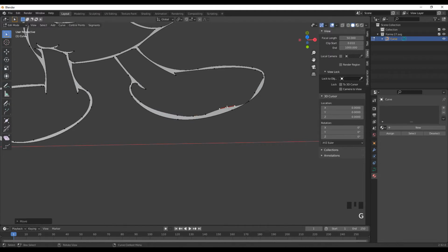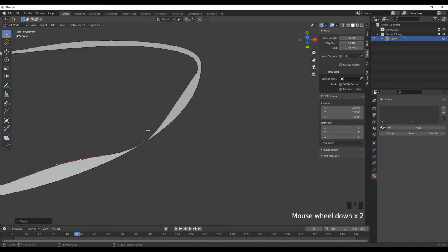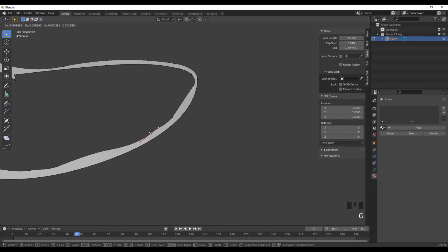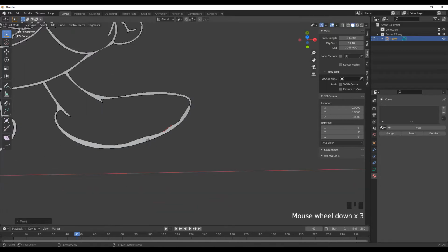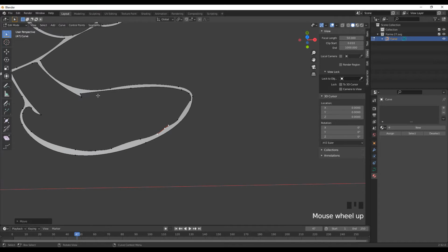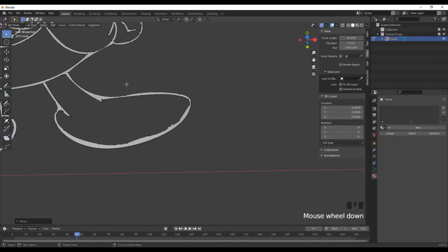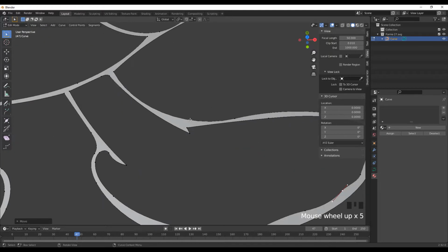It's a quick and dirty work. I will not do exactly what you will have to do. It's just for example, and why I'm doing this is that I want to create a thickness enough in order to be able to print the object. If you take a look at part 1, you will understand why I'm doing that, because when you create a shape, if this is too thin right here, you will not be able to have a clean print. Your nozzle will be too big in order to print it. So we want a correct object.